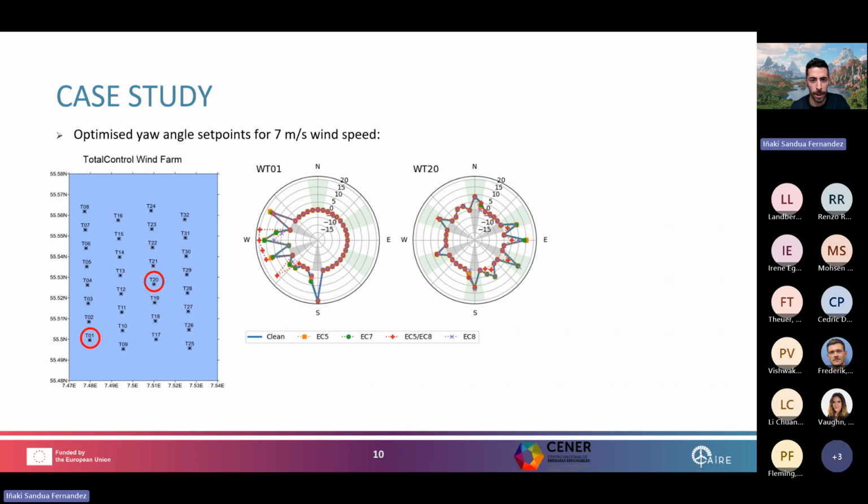As I said before, when there are no wind turbines downstream, yaw is 0. Whereas I haven't said this before, but yaws are limited between 0 and 20 degrees in FLORIS. We have run simulations setting another limit, but conclusions are also the same ones.